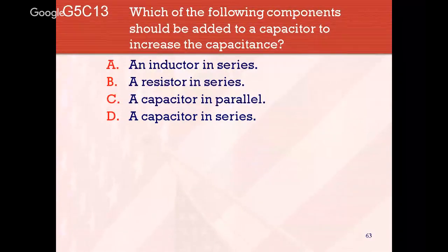But what happens if you want to add capacitance? You want to increase that capacitance. It acts different than resistors. Resistors in series, you can add resistance in series to add resistance in that circuit. But when it comes to capacitors, it's just the opposite. You add a capacitor in parallel.